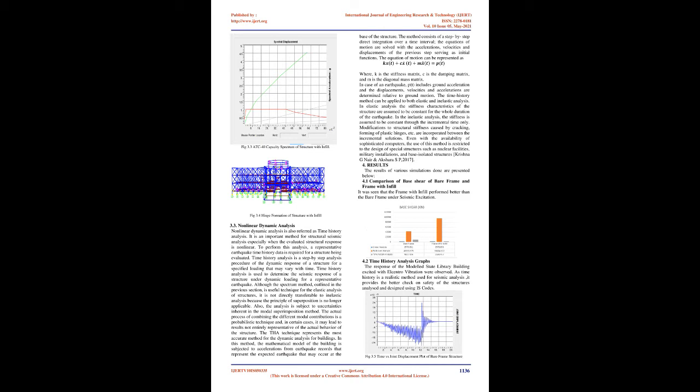3.2 Nonlinear Static Analysis. Nonlinear static analysis, also known as pushover analysis procedure, is mainly used to estimate the strength and drift capacity of an existing structure and the seismic demand for this structure subjected to a selected earthquake. Pushover analysis, which is an iterative procedure, is looked upon as an alternative for the conventional analysis procedures.